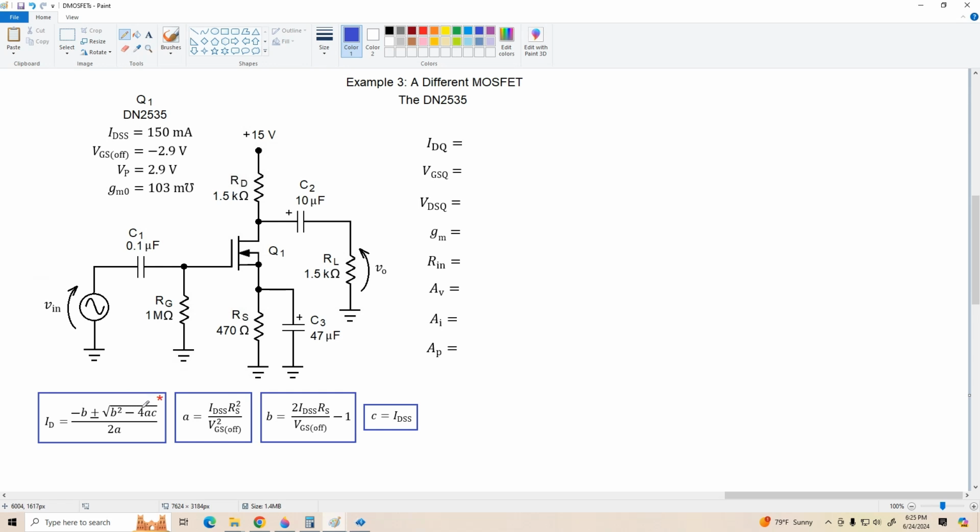So this is something you have to watch out for. Sometimes that happens, and that's happening here because we're operating very close to the vertex, and our ID times RS line is very horizontal down there. So it's something to watch for, but it'll be interesting to see what happens if you try this approach and see what you come up with.